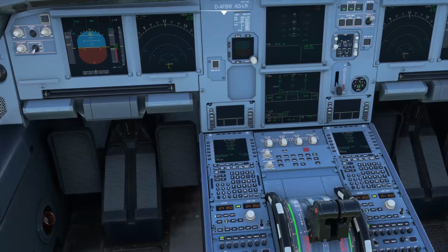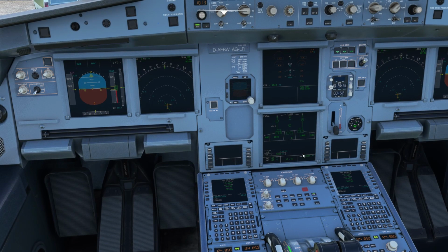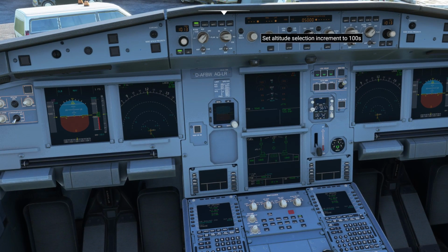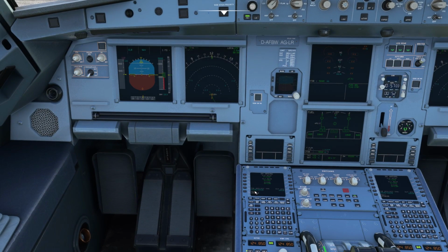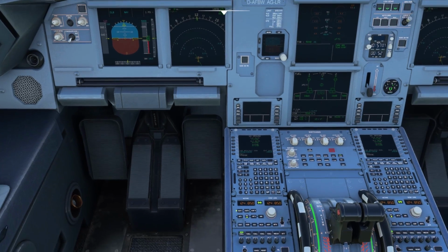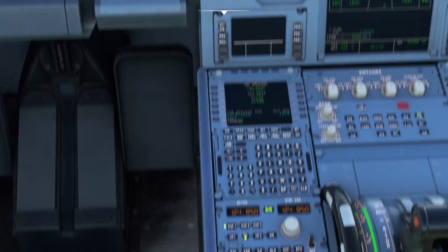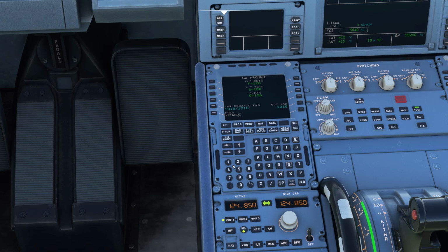It will register that you're going around, and then you'd probably have an altitude already entered in, and you'd select managed altitude, and the aircraft will just climb to that altitude. But once you hit 1,018 feet, it will then tell you to change to lever climb. So what we're going to do is just bump that up a little bit, and I'm going to put it as, you want it roughly about, from what I understand, about 1,500 above any runway.